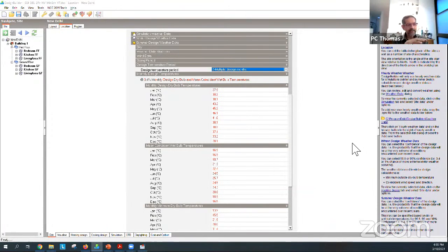Okay, so just to add to that, EPW is only a format. You have reference weather files which are calculated by looking at 10 years worth of data, but there's a TMY format, an AMY format, an IWEC format, and there's many other formats. They are done by academics. They write research papers on this and say this is good for that, that is good for that. EPW just takes that data and puts it into one text format, which the simulation engine can read.